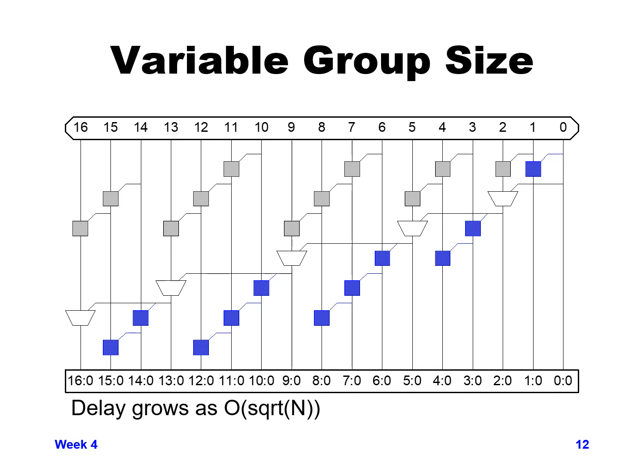And we saw that at least for a 16-bit adder, it improved our delay from 16 stages down to 9, which is relatively decent. But in this particular scenario, you can see we actually have broken up into one additional group, but we've varied the size of the group. So we have larger groups kind of in the middle and a little bit smaller on the outsides.